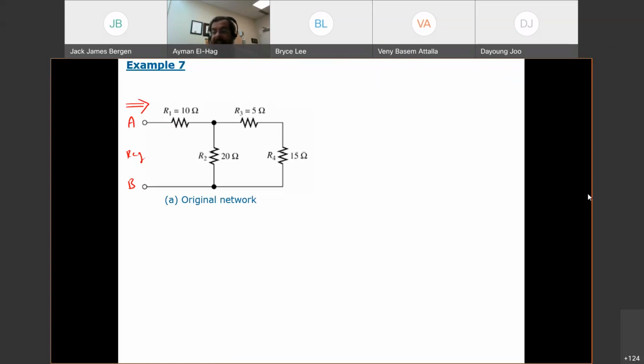Okay. It is neither. Why neither? This is why I want to stress that, before you find the equivalent resistance, we need to understand, very important, how to judge. Now, R1 and R2 share one node. They don't share two nodes, so they can't be in parallel.